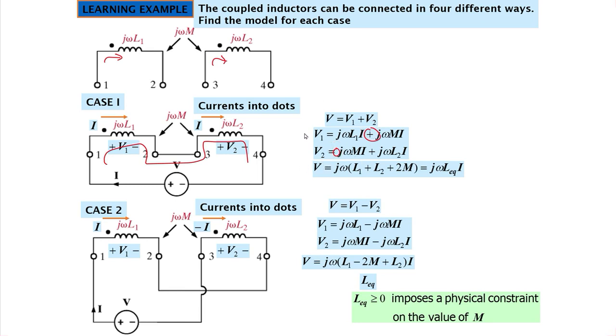But if we had a connection like this one, in this case the current is this. So what are we doing? The current is leaving this second node and entering this first node. Okay, so we will have a minus sign with it. So this must be generalized. For leaving and entering, it should be negative, and for entering and entering or leaving and leaving, it should be positive.